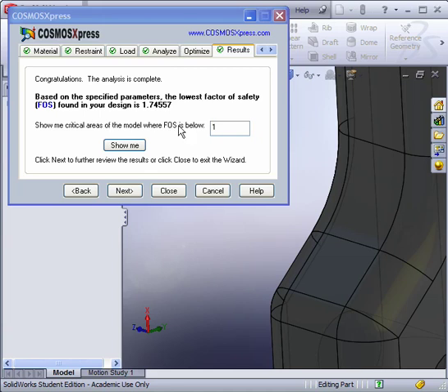Now here we have a factor of safety, and in an engineering course you start to learn about factors of safety. A general one that's non-critical, for example, might be only a factor of safety of 2. That's what you see a lot in industry for things that aren't terribly dangerous. In this case, this isn't something someone's going to hurt themselves terribly, so let's stick with this safety factor of 2. Now, if you're doing something for NASA, you might be requested to have a safety factor of 8 if it's going to go on the space shuttle, for example, because it has to endure tremendous amounts of forces or pressures.